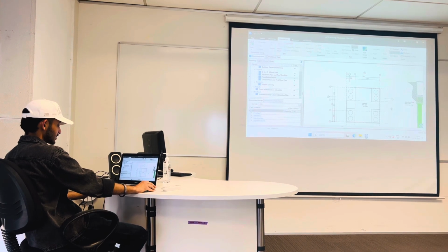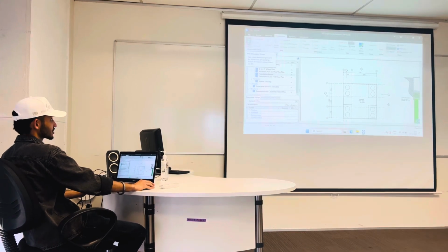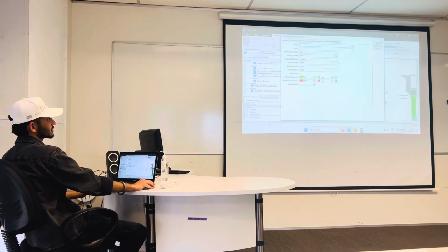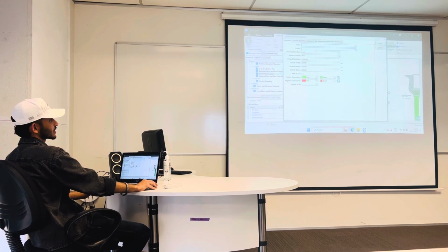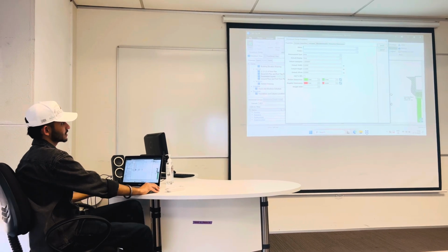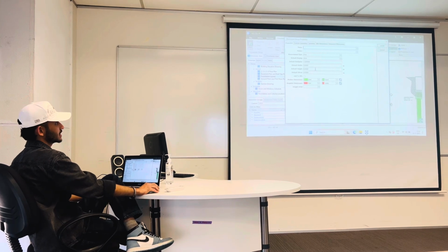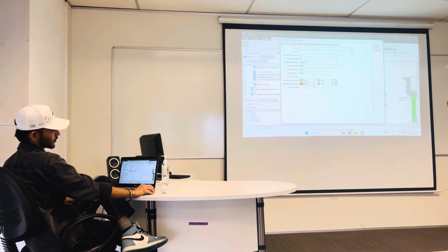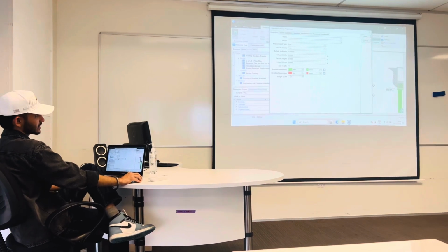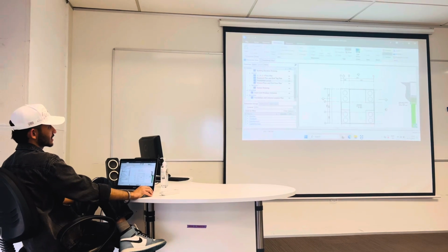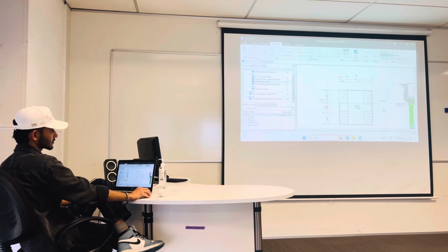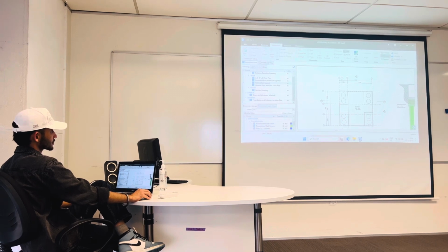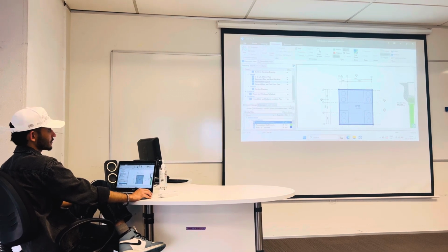So in dimensions, what we do is we add a dimension by clicking on add dimension group, and then we insert the name of the group. Then we put the folder and subfolder, and the measurement type, default display, default multiplier, width, this and that. Then there are indications for positive dimensions and indications for negative dimensions as well. But here we have some already, I have made some dimension groups in which I will choose the foundation base concrete.